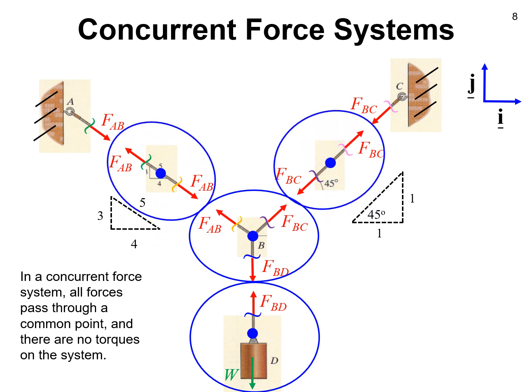And likewise, if we look at those cable segments, either the segment of AB or the segment of BC, in each of those cases also, the forces pass through a common point somewhere in the middle of that cable section. We will also note later on, we will study force systems that are not concurrent force systems, and in those cases we will also have to study the sum of moments, but for now in this module we'll focus on concurrent force systems, and therefore we have only the sum of the forces to accomplish at this point.